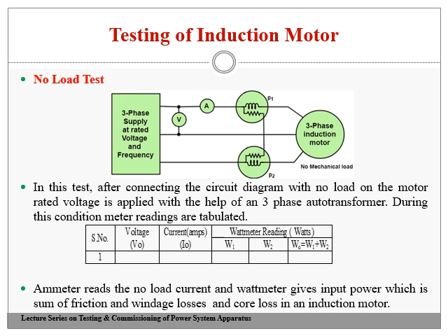Let us go for the next one, the no load test. Now this no load test is conducted on an induction motor to determine some of its performance parameters, that is, the no load current as well as the no load losses that exist when it is operated at no load condition. These parameters will help in finding out the equivalent circuit parameters of an induction motor. This test is also called the rated voltage test. Now we'll see how it can be conducted.